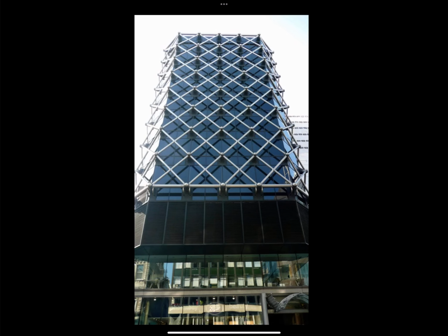This image also shows another strategy that could be used, which would be not to have a water-filled structure, but to design the glazed envelope of the building to have the fire rating, and this then would be a flame shield to protect the exterior structure from the fire inside.